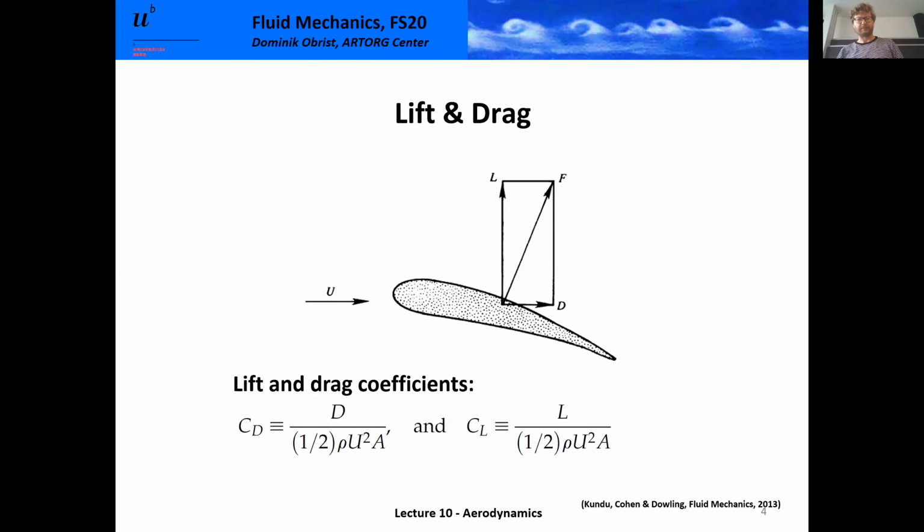And that result said that the drag of such an object divided by this quantity, 1/2 rho u squared times A, where A is an area, I will talk about this later on, what this area exactly is, that this ratio is a non-dimensional quantity, and that we typically denote it by the variable CD for drag coefficient. Or in German, you so often see CW for Widerstandsbeiwert.